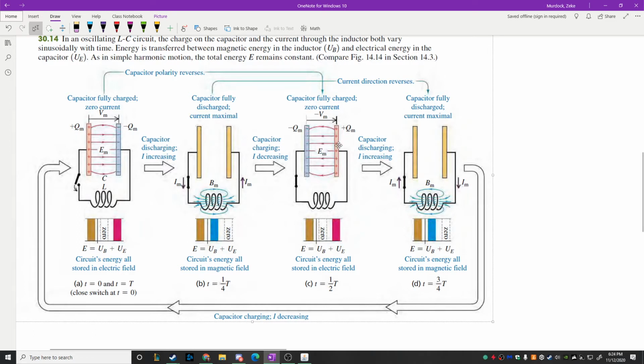And that current will basically flow until there's no charges on this capacitor, but the current will kind of continue to flow because, again, that current has a type of kinetic energy, momentum, however you want to put it, or inertia, due to the fact that there's this inductor here that has a magnetic field, and that magnetic field can basically deliver energy back to the system, charging the capacitor plate back to the initial state. So you go all the way back around to the beginning again.